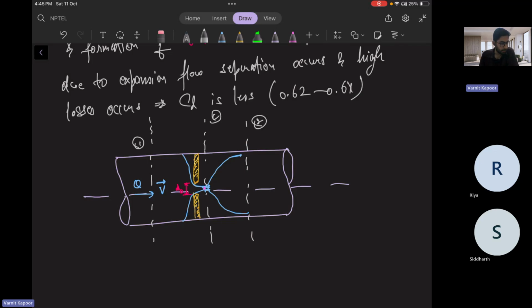So here what is happening, because of sudden obstructions, eddies are forming. We have understood this concept of eddies in the last tutorial. And finally the fluid tried to expand with the flow rate of Q. Velocity will be the same because the pipe diameter is the same eventually, but there will be a pressure drop because of the presence of losses in the pipe.